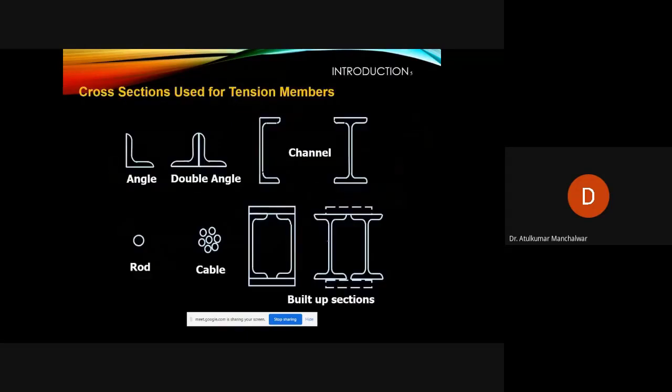Next. Yes, a very important topic is the cross section used for the tension member. So angle section, and if you use the same angle two times, a double angle section, for larger forces. Channel section, I section, rod, cable. Okay, these are built up sections. Mostly I will tell you,